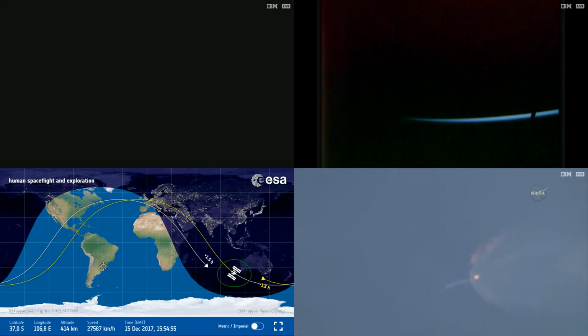You can see here the exhaust plume of the 8 outer engines spreading out, and then a little bit behind that actually the center engine, spreading out as the atmospheric pressure at that altitude is lower than the sea level pressure that the engines are optimized for.